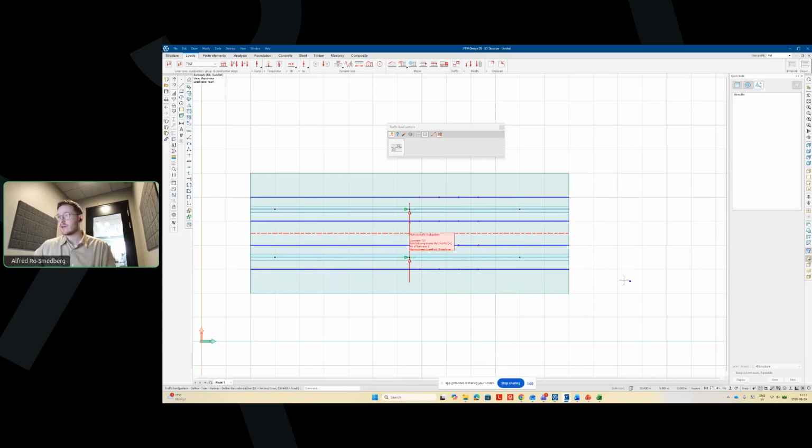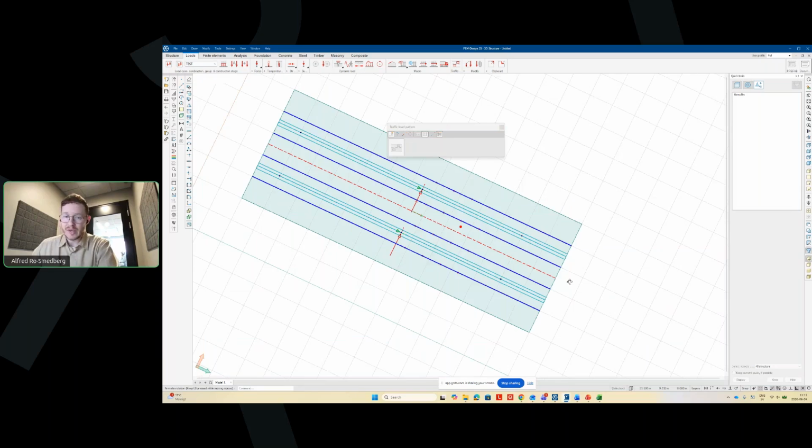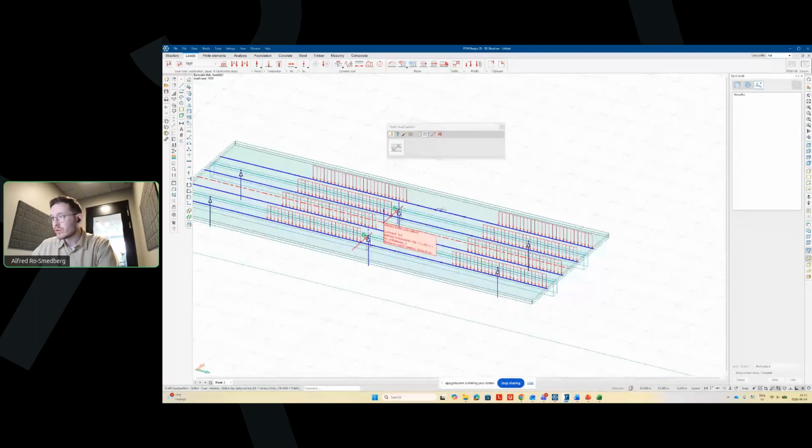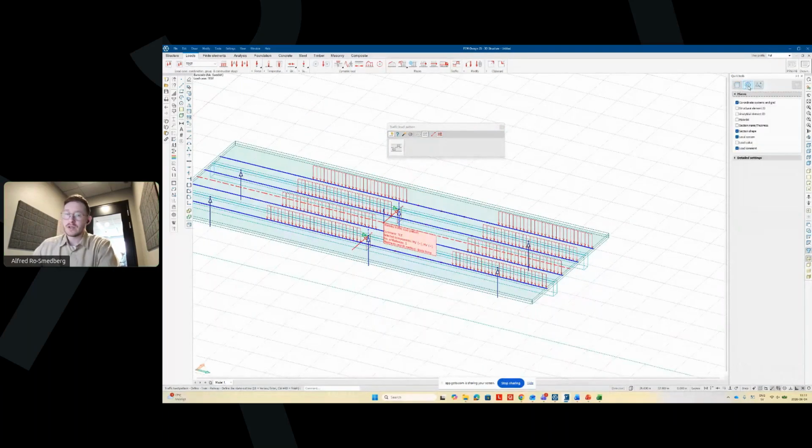And then when I click enter, we can see that we have generated this kind of load pattern. I've had some visual bugs here lately for the traffic loads, that it doesn't show up immediately. What you can then do is to go over here to the right into display settings, and you can, for example, turn on load value.